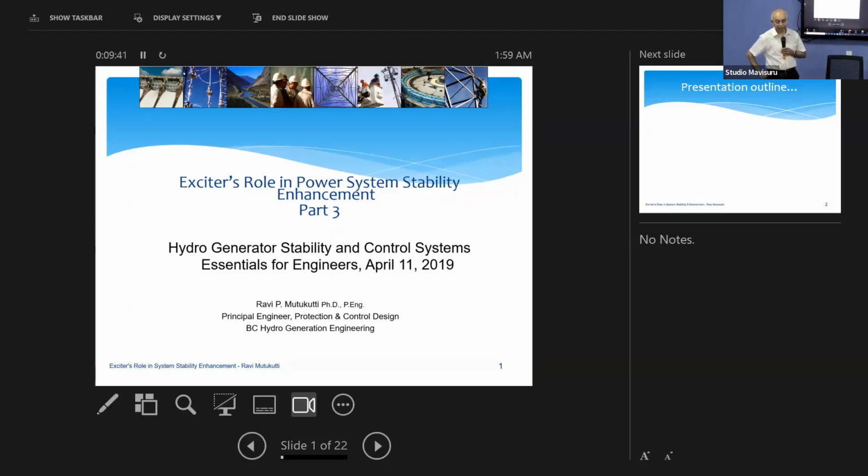My own opinion is you have many problems in the Sri Lankan power grid. Among the many, the biggest one is frequency stability. That's my opinion, right? My opinion is not just based on opinions. I did check, I did test 5 generating stations, 4 hydro stations and 1 diesel station. I found frequency instability problems on not all 5, except 1.